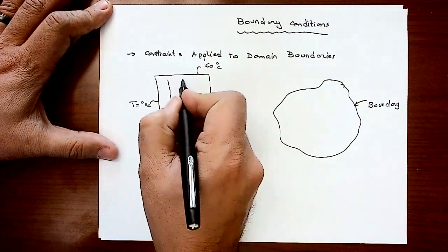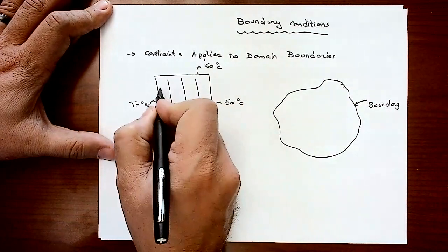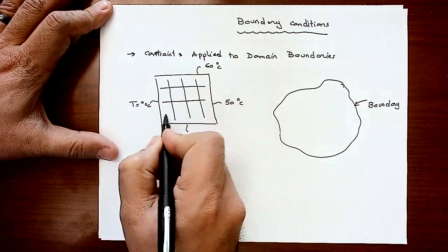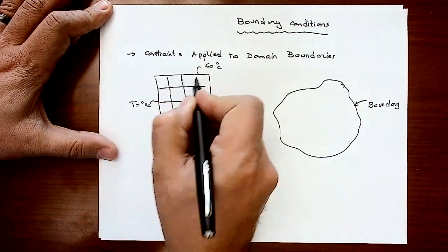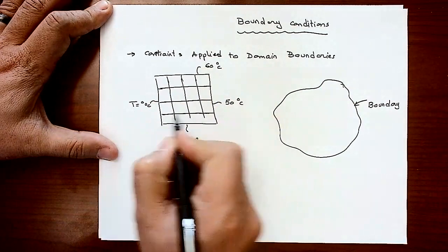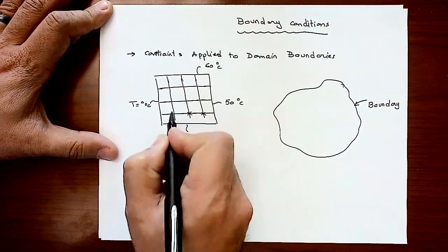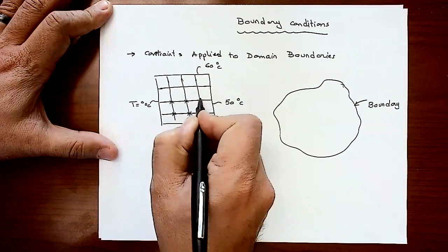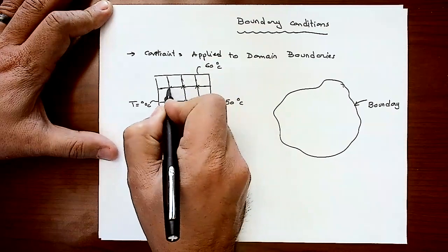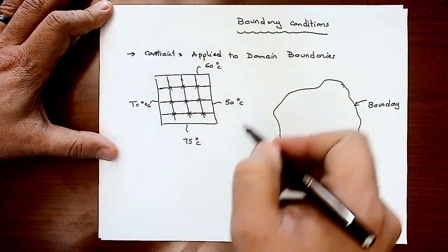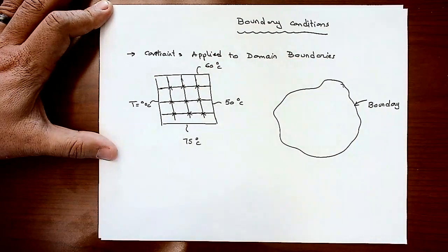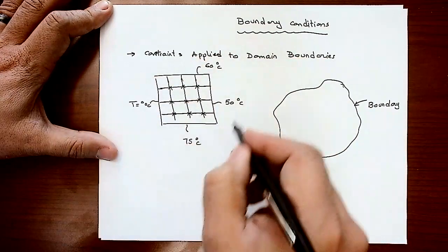So you're going to set up your grid or mesh, right, to determine your nodes to get the approximate solution using the numerical analysis here. So you're going to get the temperature at these points here. What the boundary condition is telling me here is that the temperature within that plate has to be within the boundary temperatures. So you have to get your temperature somewhere within that range.